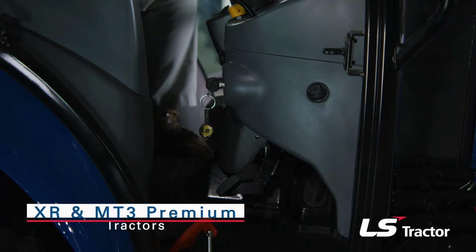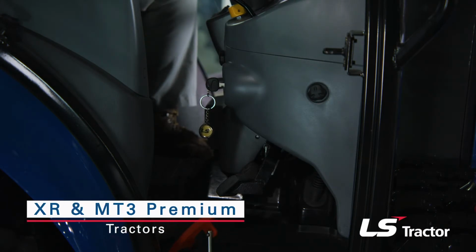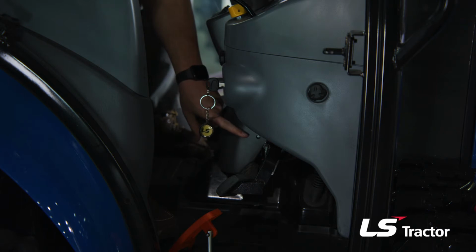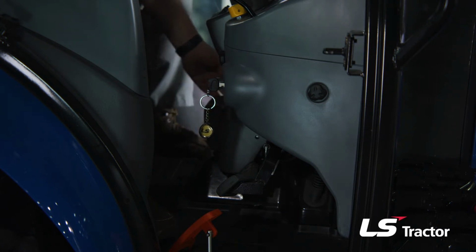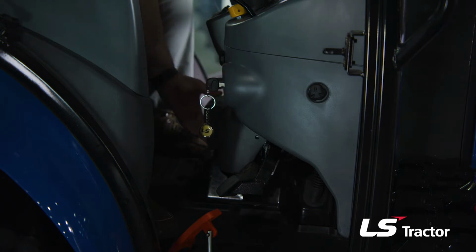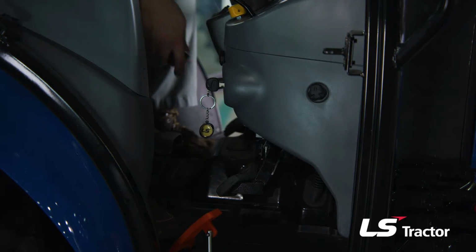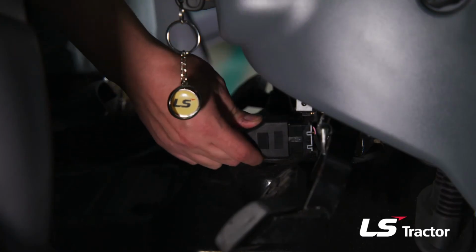To access the diagnostic port on the XR and MT3 premium model tractors, you will first need to remove 1 screw from the right side and 2 Phillips head screws from the left side. This panel will then lift up and out, allowing access to the OBD2 port on the bottom right-hand corner.